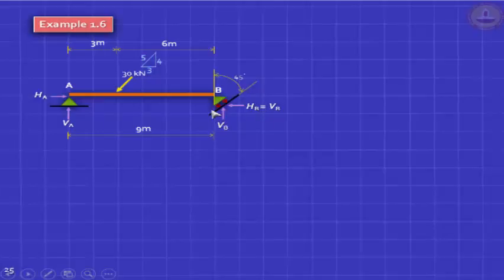These two are related to each other because the resultant reaction must be normal to this plane, because it is rolling here and cannot have a restraint. If you resolve VB and HB, it will point in this direction. The question is to find RB, but it's nice to talk of VB and HB equal. So it's not a difficult problem.